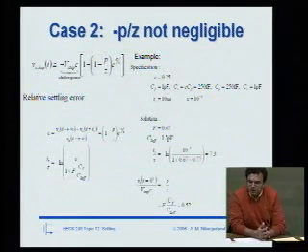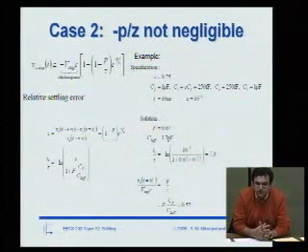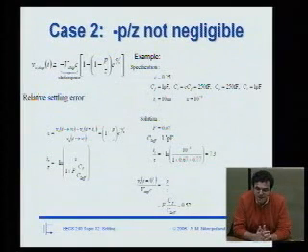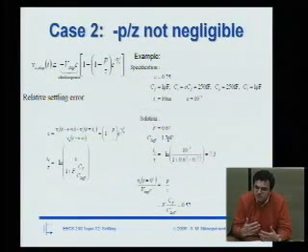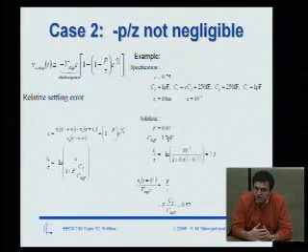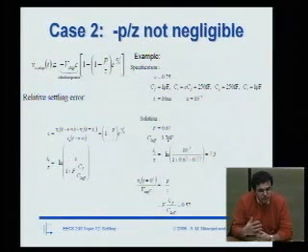Actually, it turns out there are situations where you do need an amplifier with a gain of 1/4. And a good example of that is if you're building a filter. In a filter, you have lots of integrators. And so these integrators are integrating charge, right? And their voltages are getting larger and larger. And you get into situations where internal voltage swings on your filter could get large enough so that you actually saturate out. You hit the power supply rail.